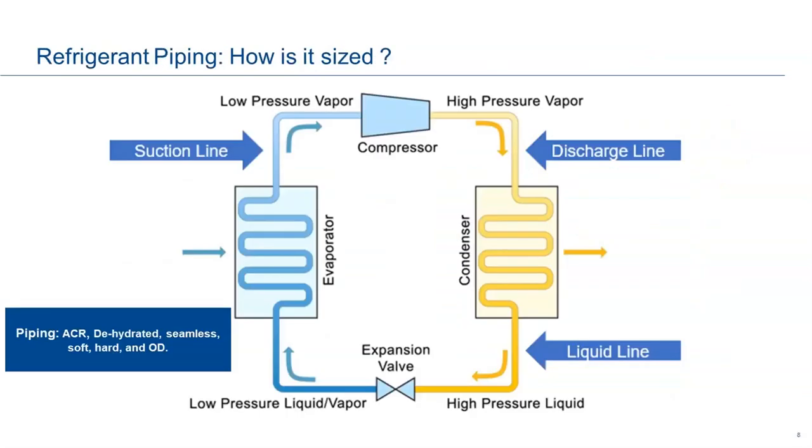So let's talk about refrigerant piping a little bit, okay? The two biggest reasons we size the pipe for what we do, and I never understood this when I first started, and some of you may have on-the-job training or went to school, are that we have to have it large enough to bring the volume to cool the compressor down, and we have to have it small enough to have enough velocity to drive the oil back to the compressor.